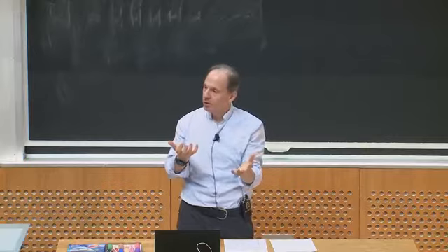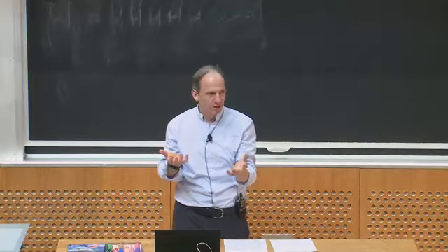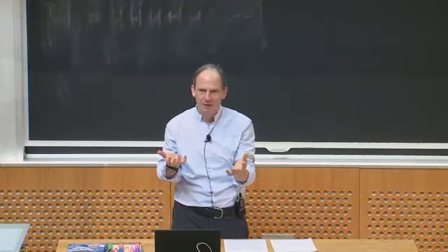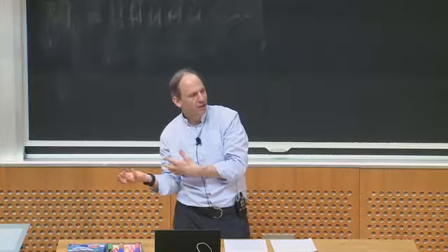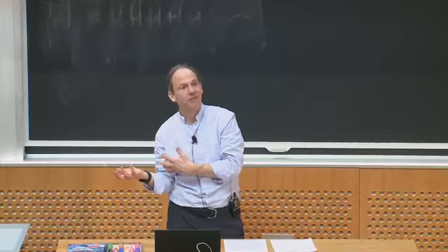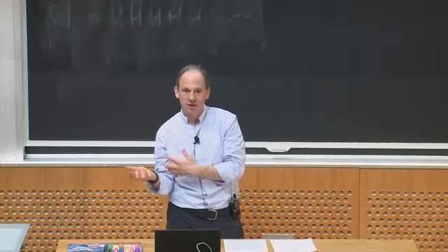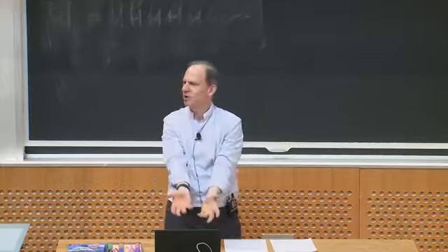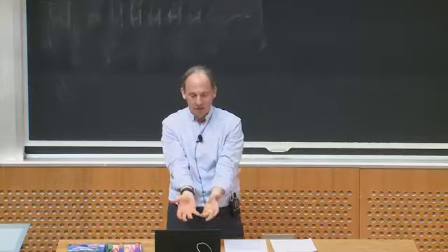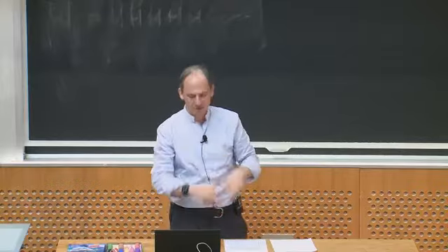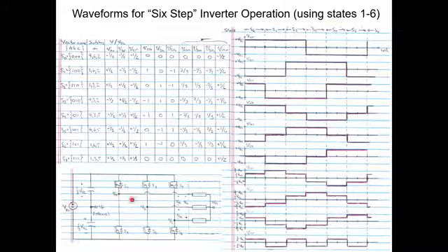Now, if you're going to put notches in the waveforms, you wouldn't try to eliminate the third harmonic, because the third harmonic is going to go away. You might try to eliminate the 5th and possibly the 7th harmonic. So the same kind of games we talked about playing with a single-phase inverter, you can play with 3-phase inverters. It's just you're doing each phase and then you're shifting that by 1/3 of a cycle to get to the next phase. Okay, any questions about that?